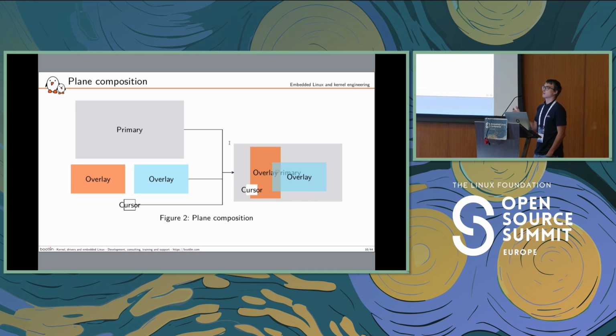If you take a look at a lot of graphic display controllers, you will see that they can grab multiple planes to compose one output. So in this case, you can see I can configure it to take 4 different planes and generate one output. This is useful, for example, for the cursor here. It is nice because your cursor is most of the time the same. You don't have to send the picture again and again, and you just have to change its position on the screen. So it's very convenient just to say to the display controller, please put this plane at this position.